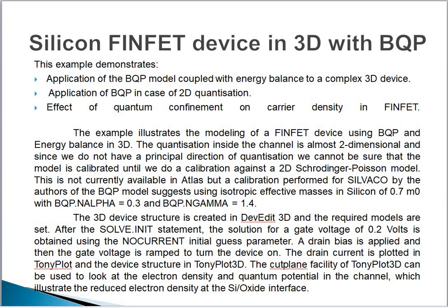The drain current is plotted in TonyPlot and the device structure in TonyPlot 3D. The cut plane facility of TonyPlot 3D can be used to look at the electron density and quantum potential in the channel, which illustrates the reduced electron density at the Si-SiO2 interface.